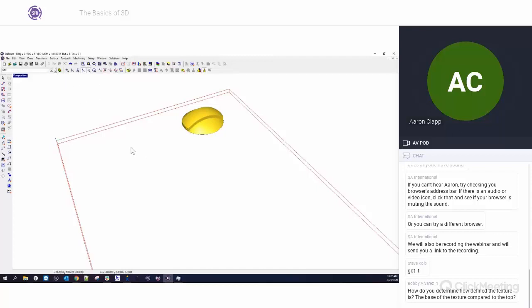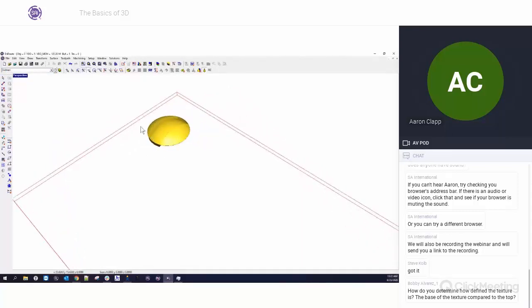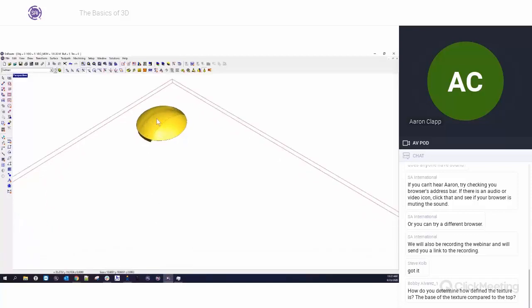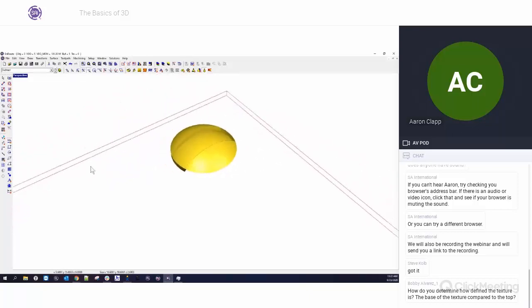So let's take a look at subtract. Now subtract is basically going to do the same thing except for the opposite direction. So instead of choosing add, when we choose subtract, which is our second option right here, subtract from relief, this is going to subtract that in an even fashion all the way down. So we got the same effect just in reverse.